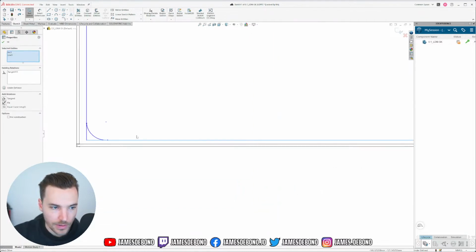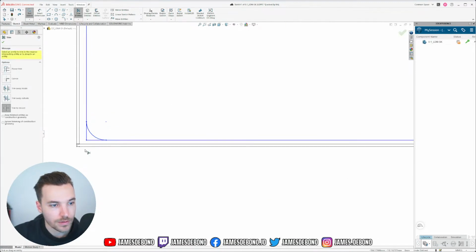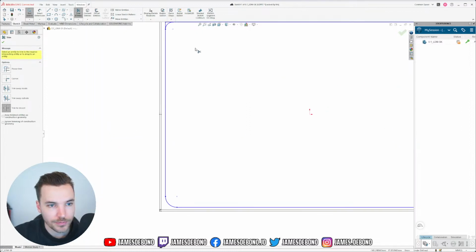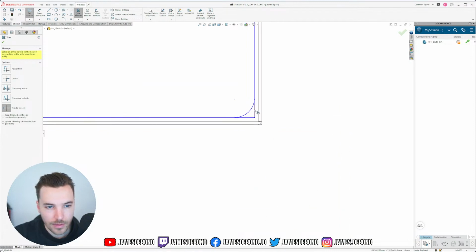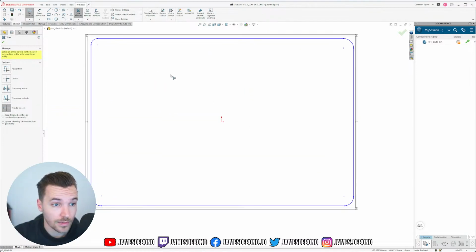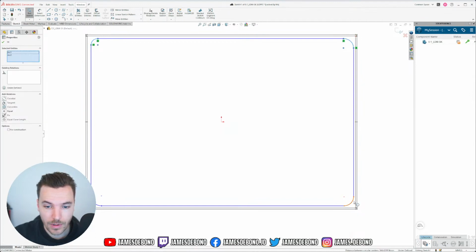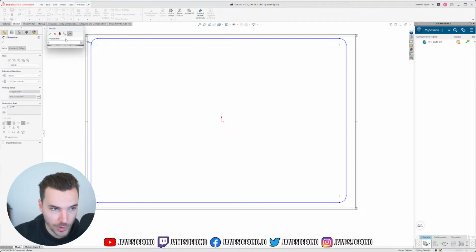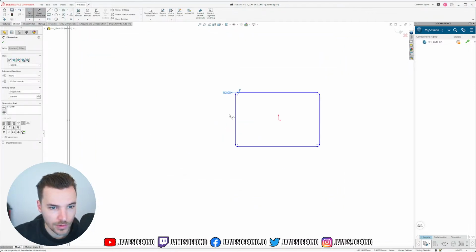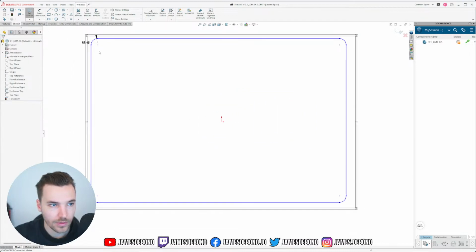So I'm just making a big rectangle with curved corners. And I don't use fillets because fillets sometimes break, and it's easier to add relations to curves like this. Gonna make all these the same size, and they'll probably be like 2mm radius. Oops. The whole thing got smaller.